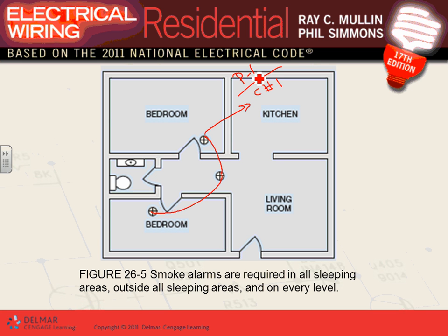Do I need one in the living room? No. Could I put one in the living room? Yeah, if you want, you just put one in the living room. Is it a good idea to put the smoke detector in the kitchen? No. So if you are worried about burning something in the kitchen, what's a good idea to put in the kitchen? Anybody can tell? How about a heat detector? I can put a heat detector here and tie it to the same system. These are not required though. Any comments, any questions, guys, on where you need smoke detectors?